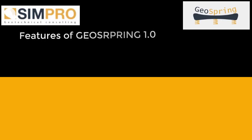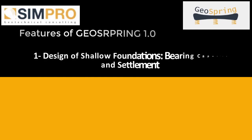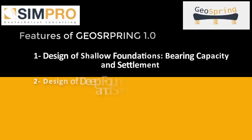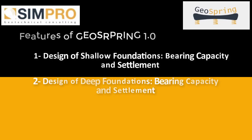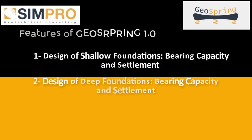So let's go ahead. Basically, GeoSpring contains 4 modules. The first module is about the design of shallow and deep foundations. So it computes the bearing capacity and settlement. The second module is about pile foundations. So it computes the settlement of pile foundations, single piles and groups of piles also.